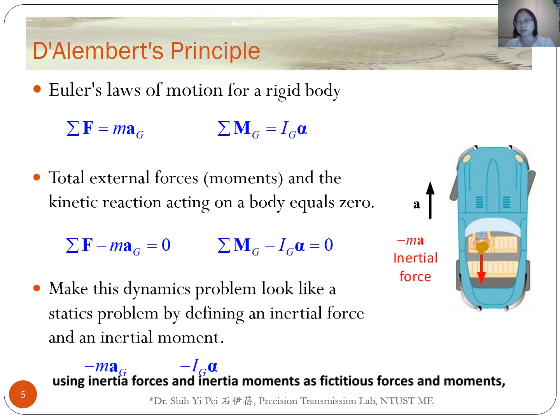In other words, using inertial forces and inertial moments as fictitious forces and moments, we can simplify the dynamic problem into a static problem. Therefore, the methods adopted in static force analysis, free body diagrams and the conservation of power, for example, can be applied in dynamic force analysis.